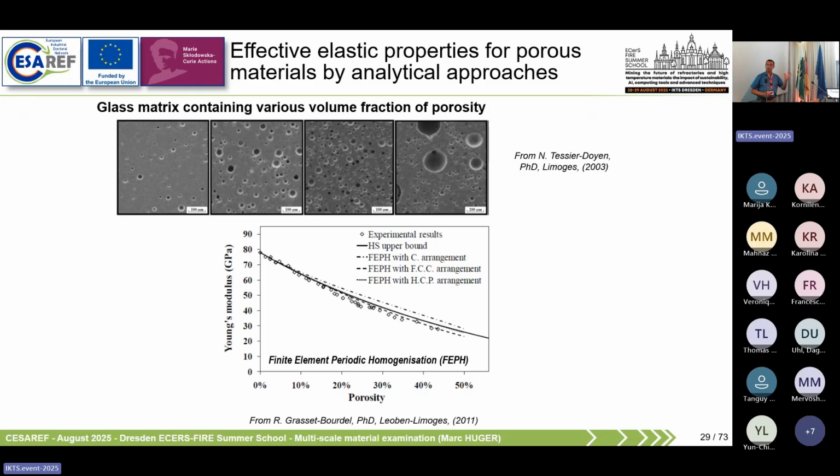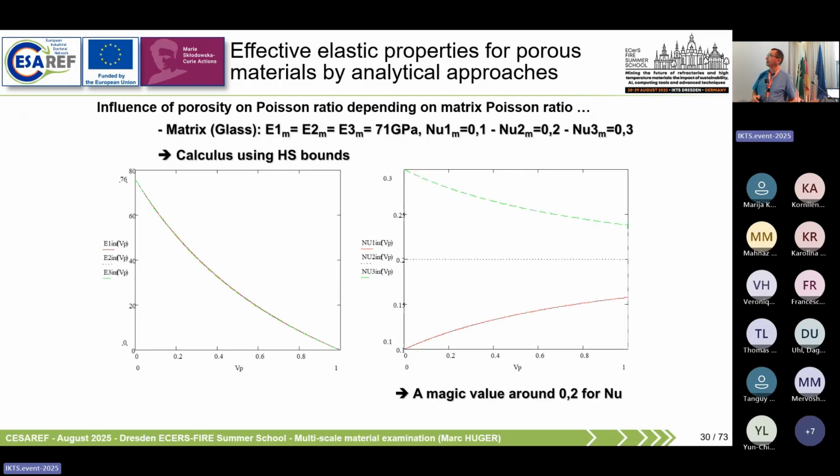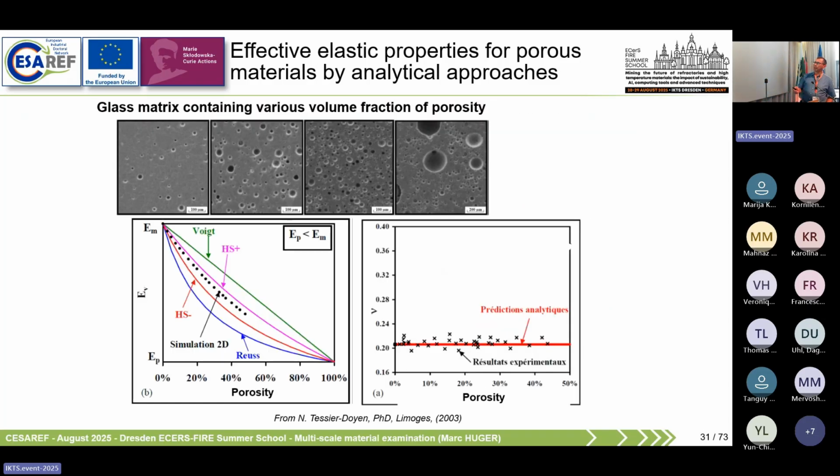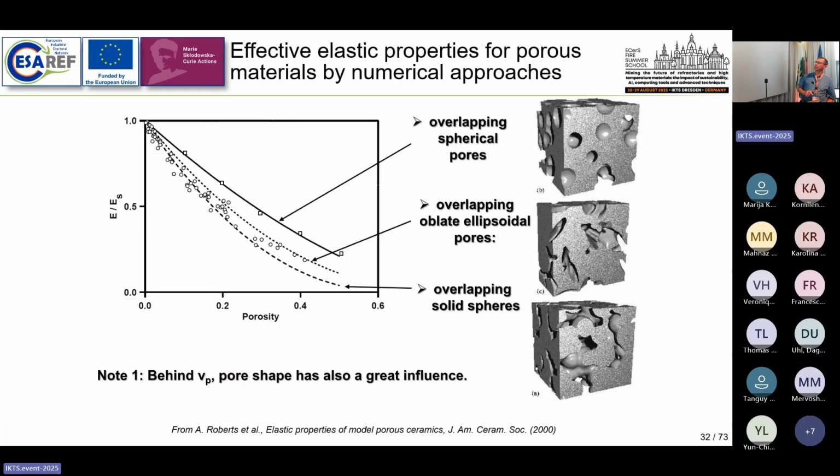If the porosity is round, you can apply different specific models, typically the one that I presented in the previous slide. But if your porosity is not round, which is the case in most refractory areas, you are not there, and then the classical model is not exactly applicable. I will skip this slide, I think. About pressure ratio, I will just move to those ones.